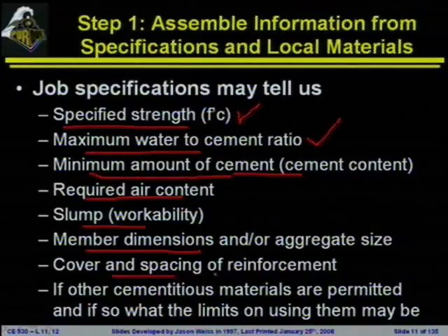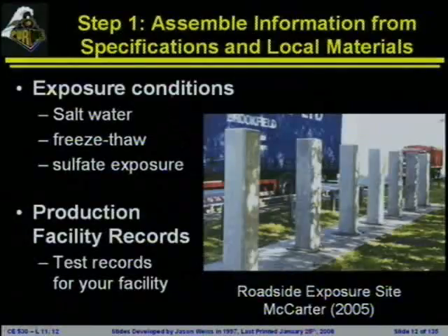They will also tell you limitations on things like supplementary materials or what time of the year supplementary materials can be used. October 15th in the state of Indiana, no one in paving operations is allowed to use fly ash anymore. That's a pretty clear example of something that would be in a specification that a producer would need to know. Exposure conditions, we're going to need to know a little bit about this.